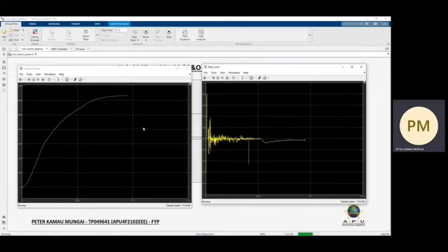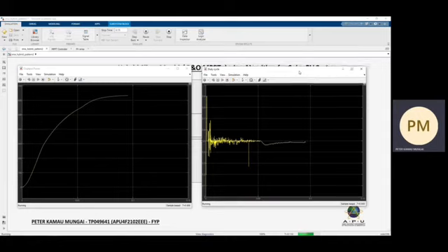After observing the power, it calculates the PV array's power by measuring the voltage and current, and this provides a perturbation in the duty cycle based on the variation of power. The perturb and observe is activated, as mentioned, after the slime mold and is able to locate the local peak. So a summary of the system is that it works through two techniques. The initial one is the slime mold in locating the global maximum peak. And finally, the perturb and observe is activated to locate the local peak, thereby enabling the maximum power point tracking in partial shading condition.